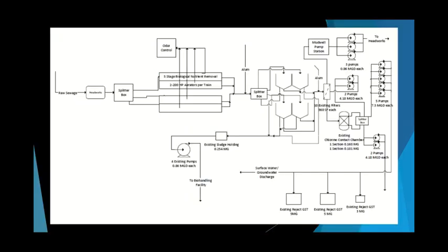The process flow diagram shown here depicts the process described on the previous slide with more specifications and detail. It displays the pump capacity and where all of the different effluent streams split off to their respective locations, such as surface or groundwater, and back into the system. It also depicts where in the process certain smaller portions occur, such as odor control and alum addition.